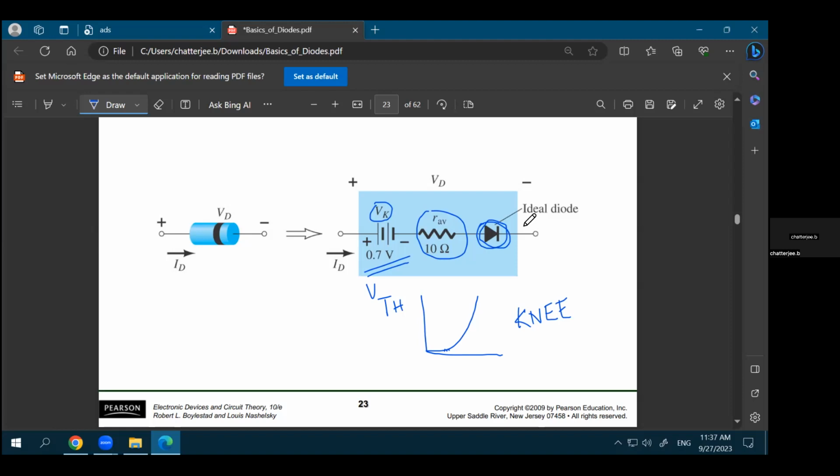Yeah. You can take 10, you can take any other value. It's just that you want to make that value as far away as you can. What you're doing is bringing it 10 times away from the primary source or the dominant pole. Okay, but then wouldn't that feel like, if our filter is like this, right, and we're placing a pole here? Yeah, your filter will look a little interesting.